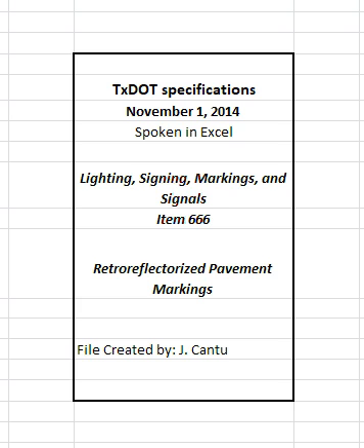2.3 Glass traffic beads. Furnish drop-on glass beads in accordance with DMS 8290, glass traffic beads or as approved. Furnish a double drop of Type 1I and Type 12 drop-on glass beads where each type of bead is applied separately in equal portions, by weight, unless otherwise approved. Apply the Type 12 beads before applying the Type 1I beads. 2.4 Labeling. Use clearly marked containers that indicate color, mass, material type, manufacturer, and batch number.